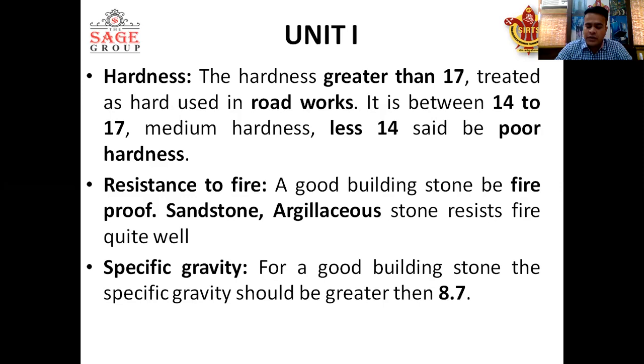As various types of vehicles move on the road, due to the continuous rubbing action of tires and friction, the stone should resist and withstand the load acting on it. So if it has hardness greater than 17, it is used in road work.